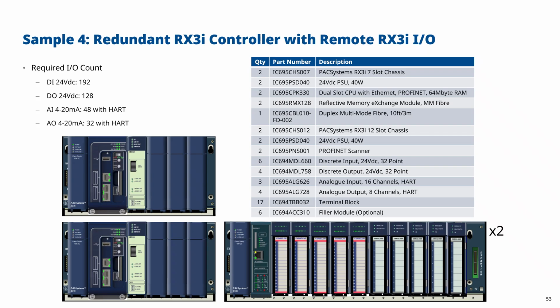And you can see physically here, you have 2 CPU racks, 2 I/O racks, and it's nice and straightforward in terms of the network architecture and the configuration. So a nice, straightforward, but high performance hot standby control system.